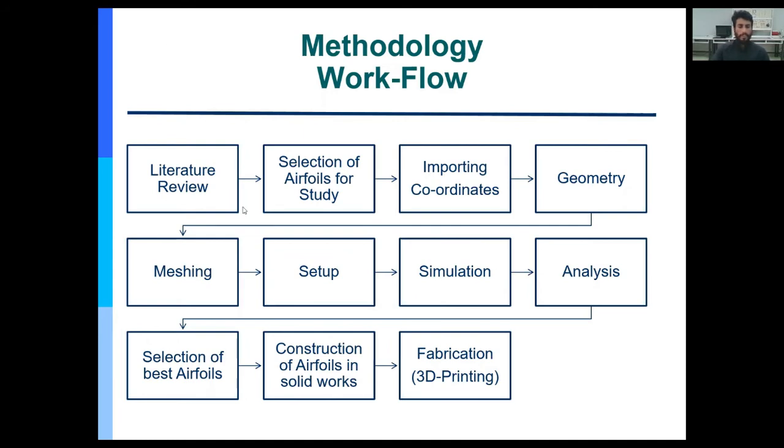The purpose of meshing is to get good results. Then we connected the meshing to the setup and completed the simulations. After simulation, we analyzed each airfoil and selected the best 2 airfoils from 10 different airfoils. Then we constructed those airfoils in SolidWorks for fabrication purposes. At the last stage, we fabricated these best 2 airfoils using 3D printing at the Sukkur IBA University Fab Lab.